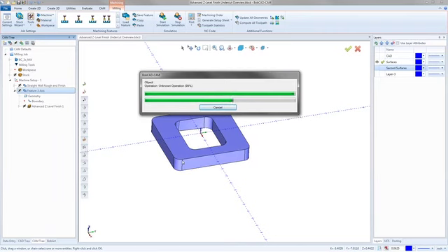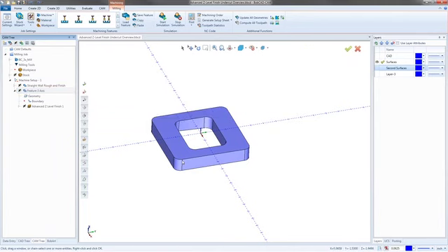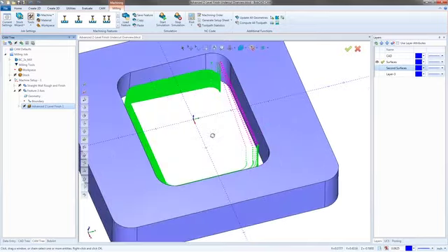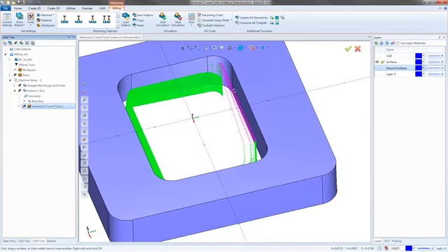The nice thing about the undercut feature is I didn't have to tell BobCAD what to cut. It just did it. It recognizes the area that needs it, and it cuts it. There are problems with this toolpath, though, where it doesn't cut as deep as we might like it to. But I will show you a way to fix that. It takes some work, and if anyone's interested in more of this kind of work, let me know, because I hate doing it, but I love showing you guys how to do it, because it's a lot of custom surfacing that might need to get done. So right there's the cut that's getting made now. And so it's just going to go in and cut.